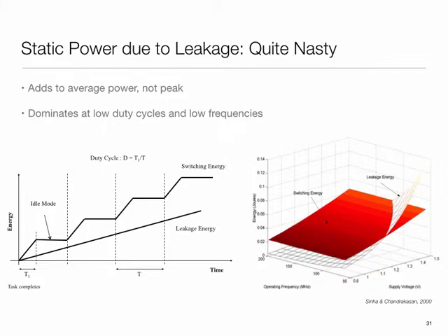If on the other hand you can shut down the system, then your better strategy would be maybe to run quickly and then power off so that you save on the leakage. And the ratio between the two, switching and leakage, is going to affect the policy. So we're going to see that later on, but these two energies are often in tension.